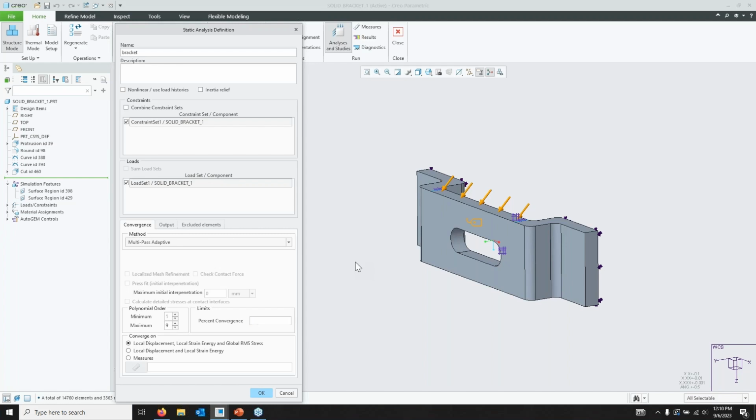So essentially, if I lower this percent convergence, it's going to make it more likely to run the full 9 times, or at least more times than I would otherwise. So lowering this, in theory, more accurate results, but more simulation run time.